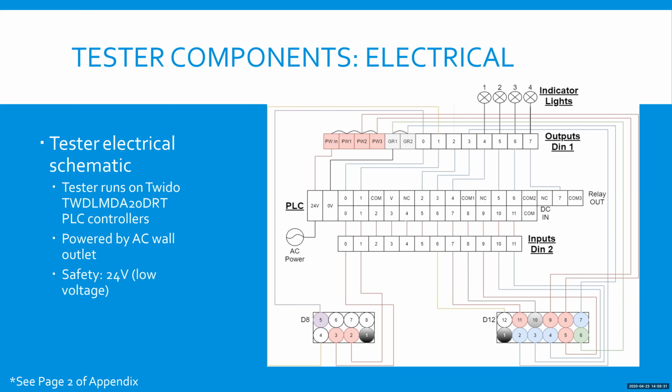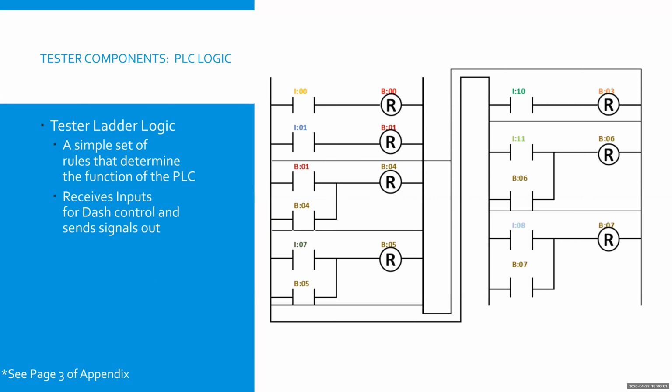So when you turn the key, which wires are going to be powered, and then when you flip the glow switch, what is going to be powered after that, and so on. After I got that, I was able to convert or change which pins are going to be inputs and which pins are going to be outputs, and I was able to then write the ladder logic.